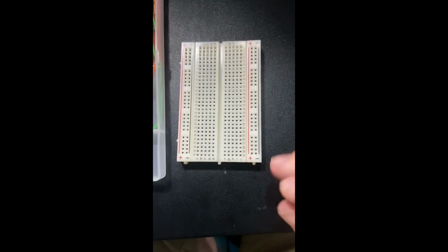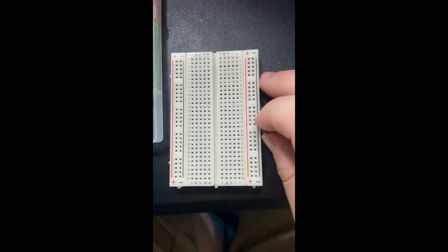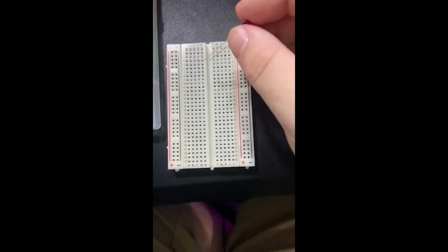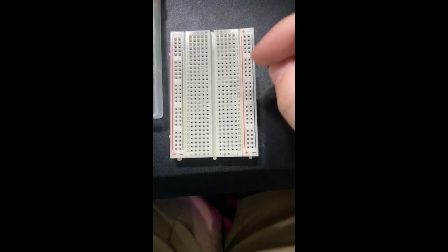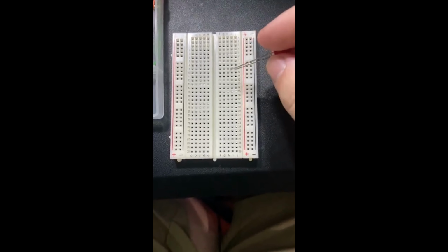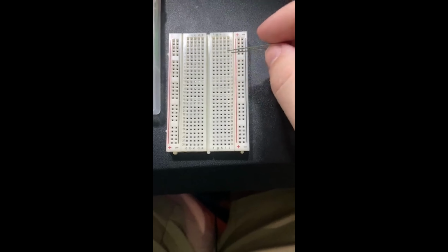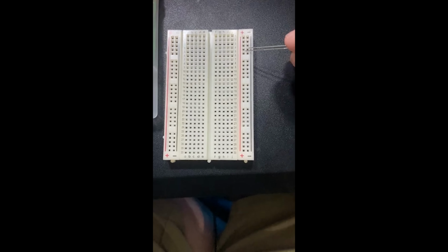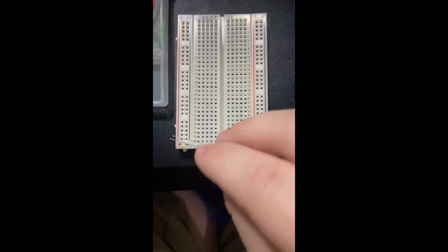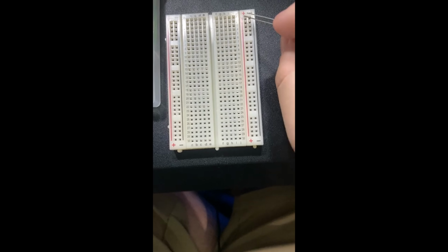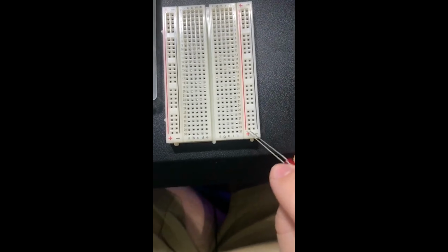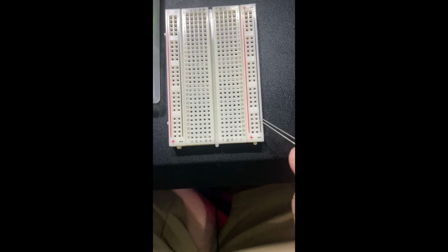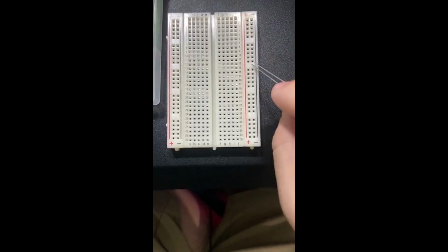To stick these into our breadboard, you'll notice that there are tons of holes in here. These holes are designed for putting the various components' leads, as they're called, into them. They're used to distribute power both vertically and horizontally through the system. The vertical aspects are these on the side here. You notice they have these big lines. When you hook it up properly, this will be all the positive voltage here and all the negative voltage on the right side as well.